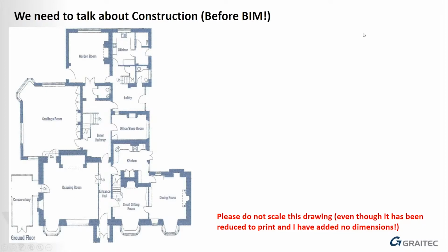for instance, if we take this plan that I've got on here, quite often when we produce our drawings, we'll always put on that little disclaimer on our drawing sheets: please do not scale from this drawing. Mainly because we might have printed it as a PDF and it's a PDF we've sent. There's no guarantee that the person that's actually printing that PDF knows what they're doing or hasn't accidentally put it on the wrong size piece of paper, etc. So what we actually have there is a plan with no dimensions, but you can guarantee there's probably somebody out there that is going to attempt to scale from that.